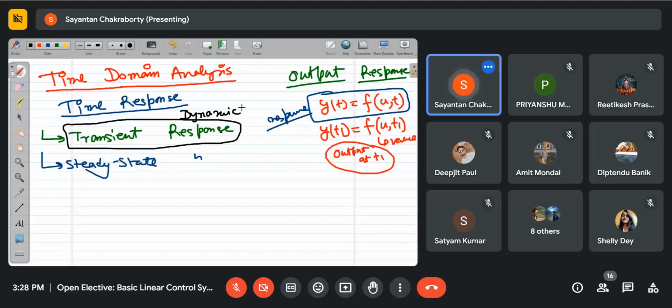So that is primary. Say you have 10 or 15 designs that ensure that, given a perturbation, the steady state response reaches the desired value. The next question comes: which design should I consider? That decision will be made based on the transient response, because the system can move over to the new steady state in a variety of ways that we will discuss.